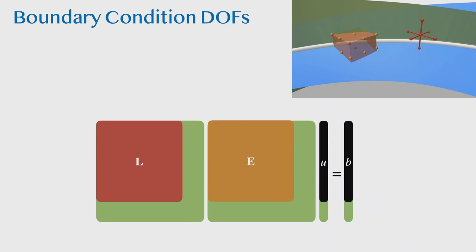And the stencil weights for Laplacian, they do stay the same, but the stencil weights for the interpolation matrix will change to make sure that you're imposing the actual boundary condition you want to impose. So that'll depend on if you want to do Dirichlet or Neumann, or first and second order accuracy of the actual boundary conditions.